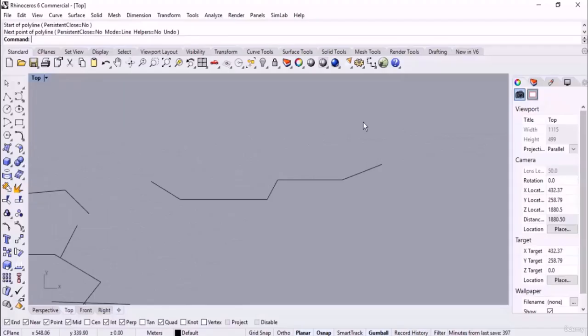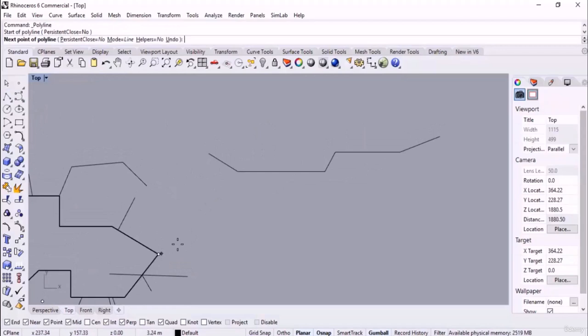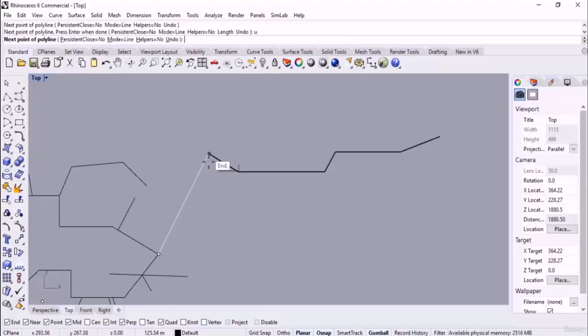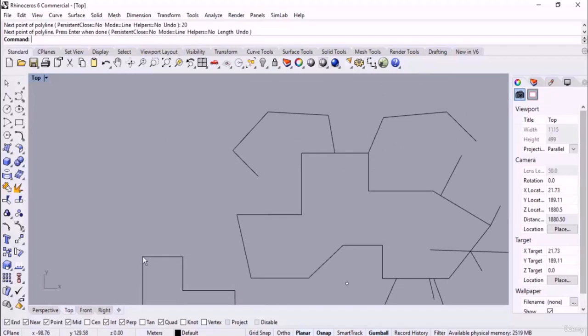And let me give you an interesting point about this. Actually, it is almost similar to this. When you are sketching a line, for example from the endpoint until this point, for example, you want to consider a gap or an offset between these 2 lines. Here if I hold the marker on the endpoint without clicking on it, since if you click the line will be sketched, I hold and I press tab, then I restrict the direction. So then you can only control the length. Then you can specify the length of your line since the direction is restricted, like 20 meters, and then enter.